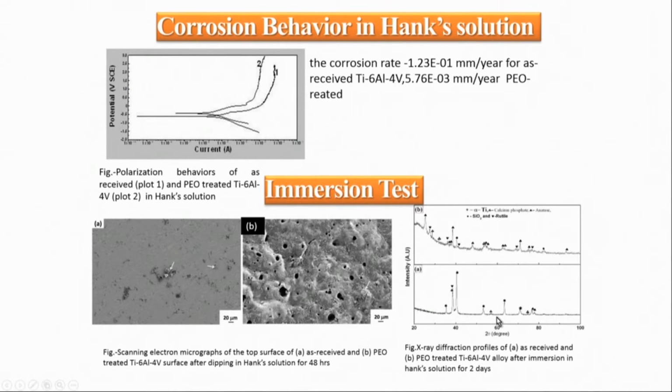So, you can understand that plasma electrolytic oxidation can be applied not only for formation of the oxide layer; it can be applied for formation of a phosphate layer if you use sodium phosphate as a solution, and for the formation of a silicate layer if you use sodium silicate as the solution. So, depending on the solution choice, you can have different types of products and compounds on the surface, not only oxide formation.